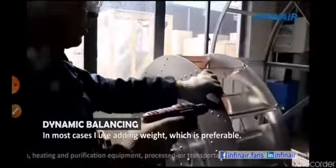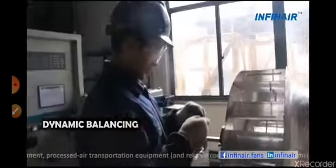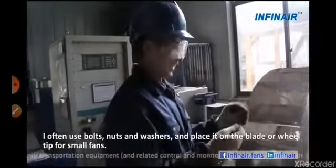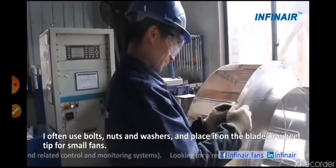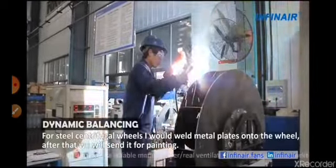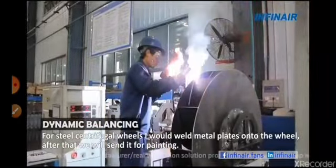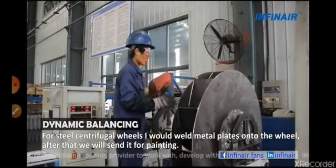In most cases, I use adding weight, which is preferable. I often use bolts, nuts, and washers placed on the blade or wheel tip for small fans. For steel centrifugal wheels, I weld metal plates onto the wheel. After that, we sand it for painting.